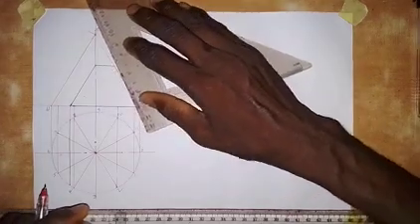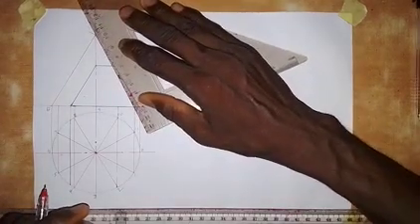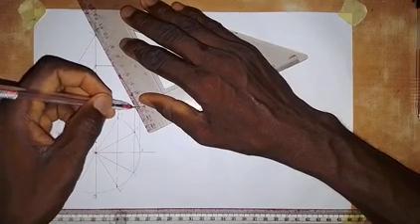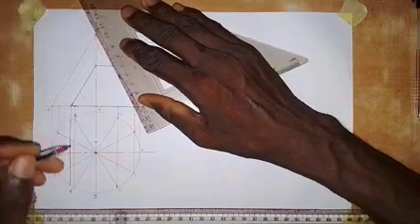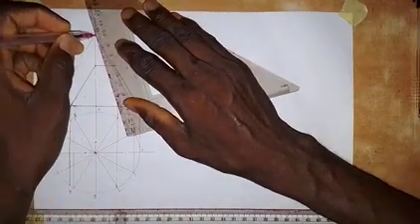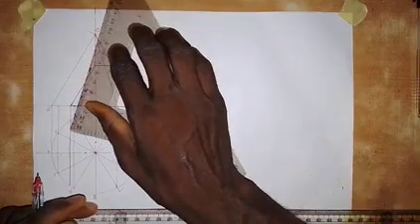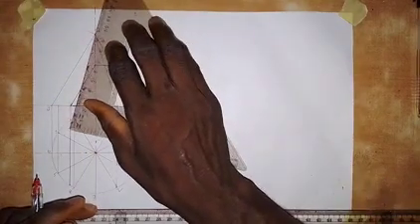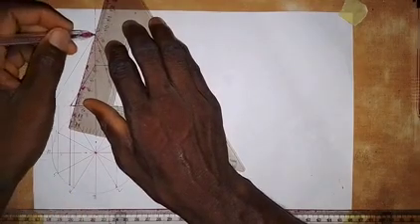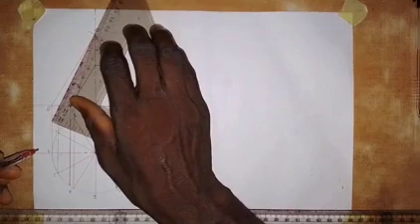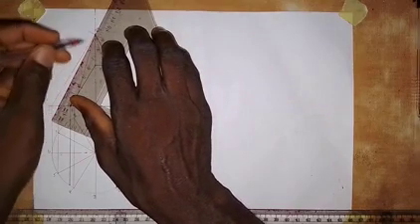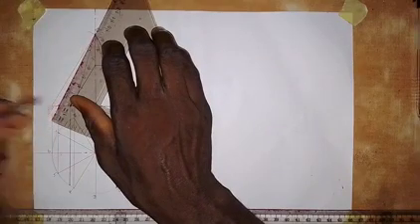Okay, so then this line 1, 11, I'm going to join it together with the apex of the cone. So I will join like this. Then 2, 10, I will also join it together with the apex of the cone. Then we also have 4, 8, I will join it together with the apex of the cone, like this. Also 5, 7, I will join together with the apex of the cone, which is not compulsory, but I just want it to be like that.